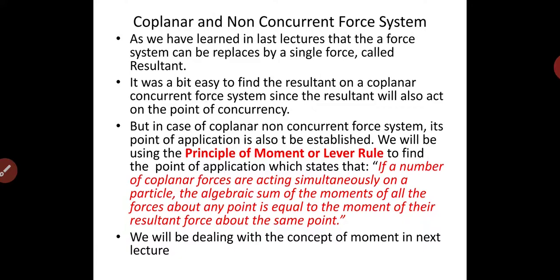We will be using the principle of moment or lever rule to find the point of application, which states that if a number of coplanar forces are acting simultaneously on a particle, the algebraic sum of the moments of all the forces about any point is equal to the moment of their resultant force about the same point. We will be dealing with this concept of moment in the next lecture.